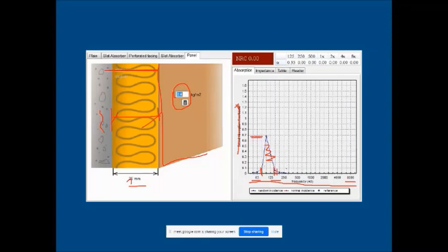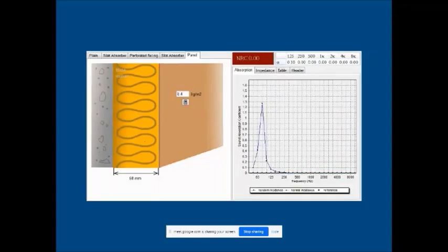But for higher frequency, it is not acting very well when we have chosen the plain simple plywood and glass wool, right? So let's take another example. In the second case, we have increased this thickness. Rest of the things are the same. We have a concrete wall, this is plywood, density is again the same, but we have increased the gap between the plywood and the concrete wall, and now we have 50 mm thick glass wool, right?